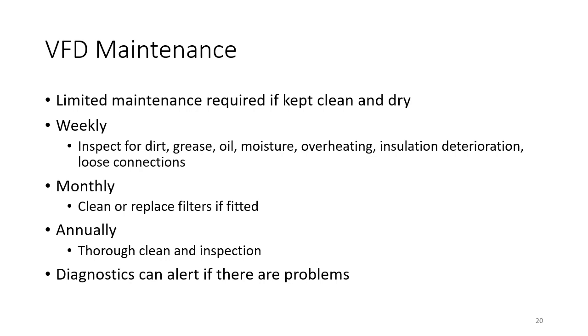And also with that, you can keep an eye on things like the power, the voltage, the frequency, power factor, and so on. So all of that can be used as a diagnostic to make sure that the VFD is operating correctly without actually having to go and do that physical maintenance. Again, if it's kept clean and dry, there's very little requirement to do anything other than the regular inspections to make sure that nothing's gone wrong.